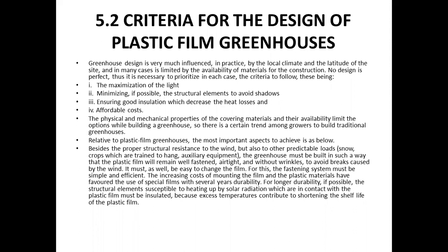Criteria for the design of plastic film greenhouses. So criteria for this greenhouse design is very much influenced in practice by the local climate and the latitude of the site, and in many cases is limited by the availability of materials for the construction. No design is perfect, thus it is necessary to prioritize in each case the criteria to follow. This being the maximization of the light, minimizing if possible the structural elements to avoid shadows, ensuring good insulation which decreases the heat losses, affordable costs.